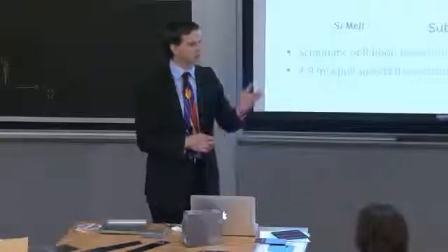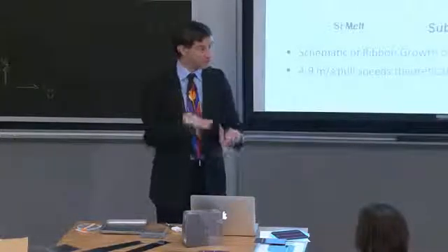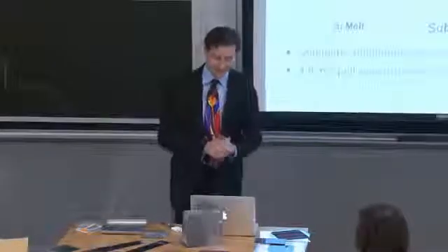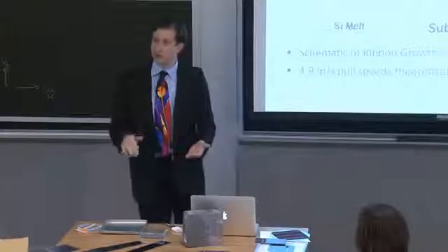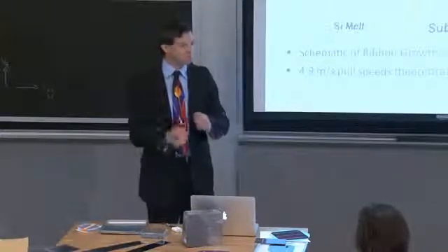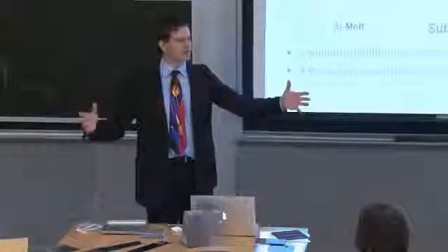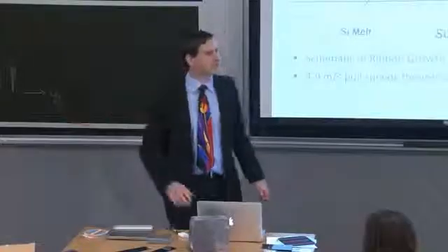One is the transparent conducting oxide, as we solved in our homework problem. We're limited in how big we can make the device by the sheet resistance of that transparent conducting oxide. Another problem that we typically run into is just that we're not able to deposit uniformly over a large area. We don't have the deposition equipment for it in our labs. We're trying to optimize a new material, and we don't necessarily worry about making module-sized devices out of it.